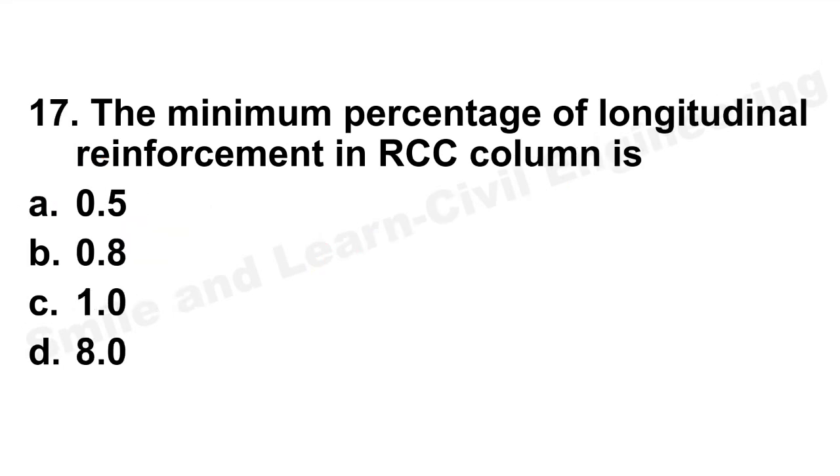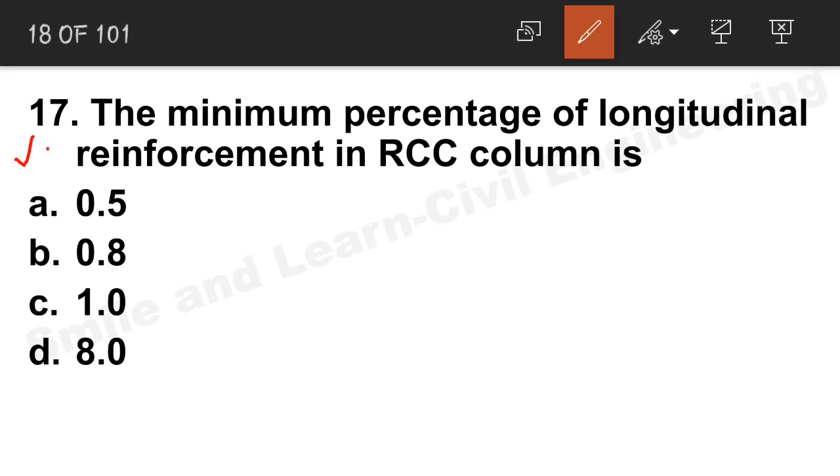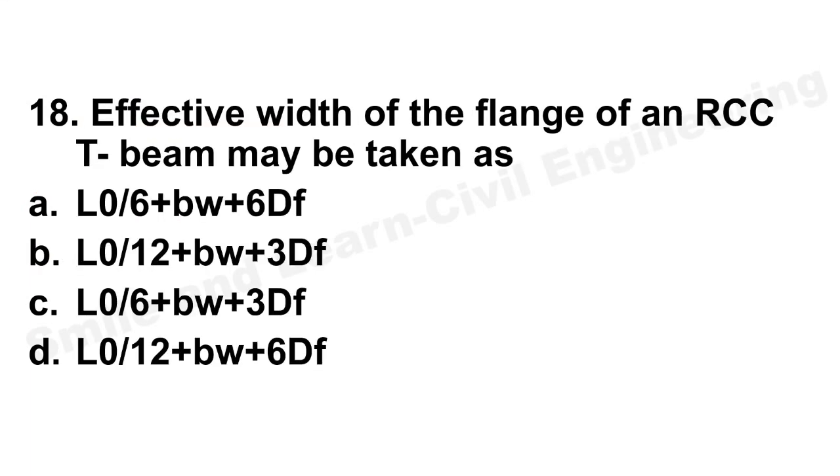Minimum percentage of longitudinal reinforcement in an RCC column. So this is another important, common question, but longitudinal reinforcement will be nothing but 0.8%. Option B. Next question, effective width of flange of an RCC T-beam.